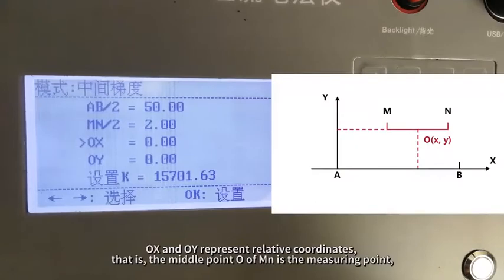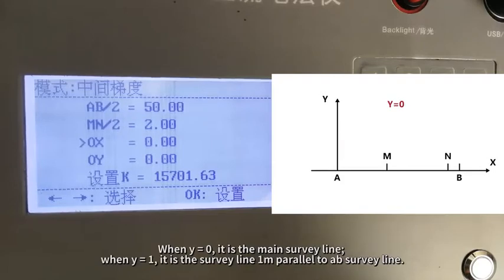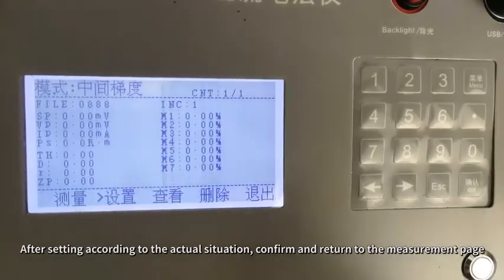Ox and Oy represent relative coordinates, that is, the middle point O of MN is the measuring point. AB is the x-axis of the coordinate axis, and the y-axis data is the parallel distance between MN and AB survey line. When y equals 0, it is the main survey line. When y equals 1, it is the survey line 1 m parallel to AB survey line. After setting according to the actual situation, confirm and return to the measurement page.